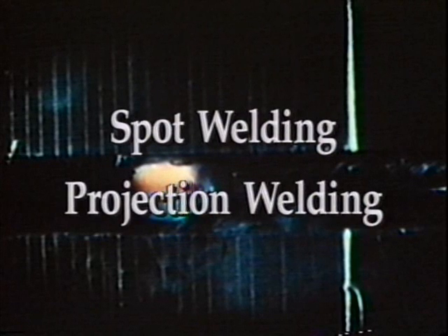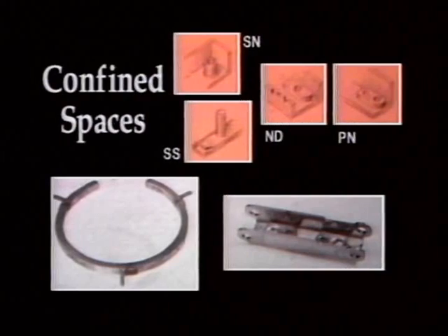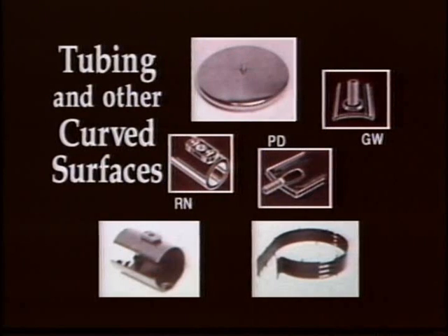The basic factors for a resistance weld to take place are heat, time, and pressure. When these factors are in proper balance, an optimum weld will follow. This applies to both spot and projection welding. Properly installed Ohio weld fasteners will provide an excellent attachment method without the need for secondary operations.